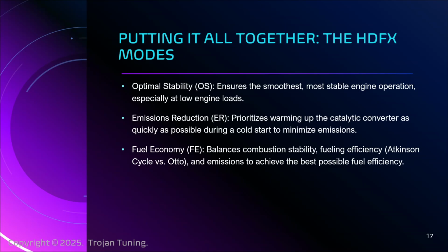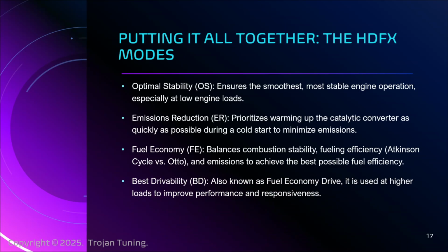In terms of when it puts the fuel in, you get about the same amount of power you would get with a third less fuel when you're running in an Atkinson cycle. The downside, of course, is that if you suddenly want power, you need to depart from the Atkinson cycle and move to a more power-based mode. But that FE mode, right, is when we are preserving fuel to the greatest extent possible.